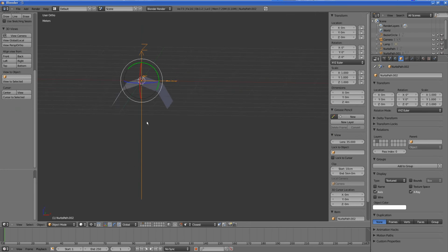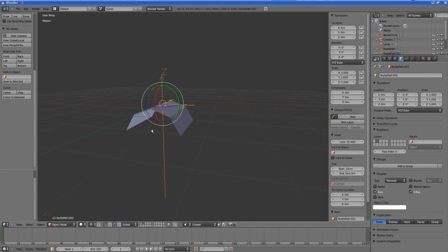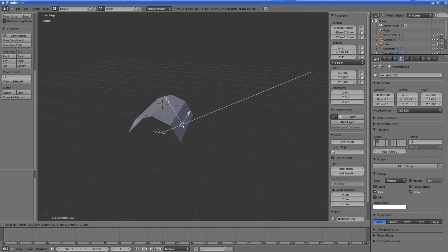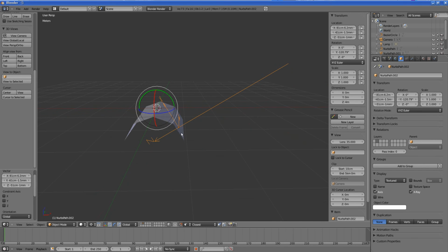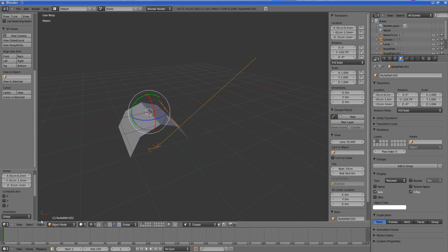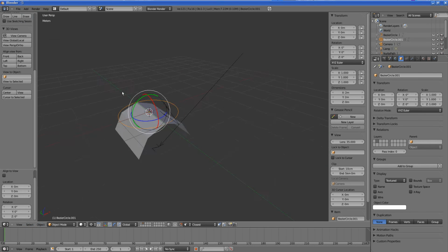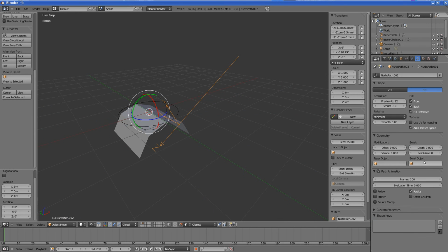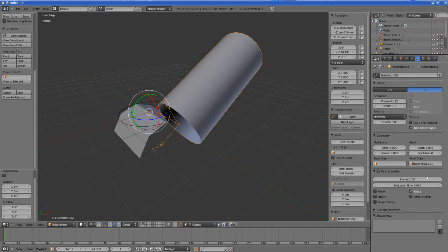There you go. Okay, now let's try to snap this G, and there you go. Okay, awesome. All right, now I want to create a sort of tentacle surface, so let's add a new curve, circle. Okay, and let's select this curve, and this should point to, now what is the name of this circle? Bezier circle 001. So Bezier circle 001.